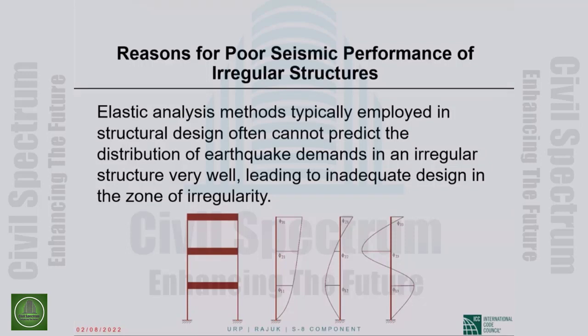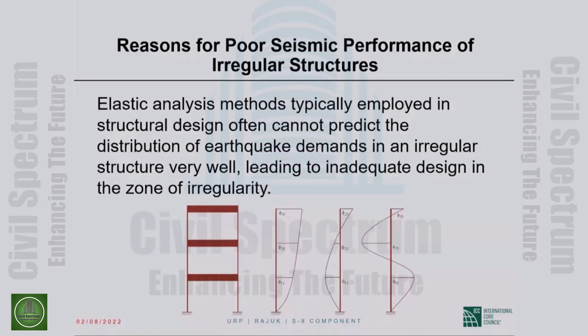The building with the two open faces and two back faces with walls that I mentioned. When the shear wall is damaged, the structural behavior is not regular anymore. So how would you find out from elastic analysis what is happening subsequently to the shear walls and, more importantly, to the columns? You cannot. There is no way you can figure out the actual force distribution after the behavior of the structure has become inelastic.